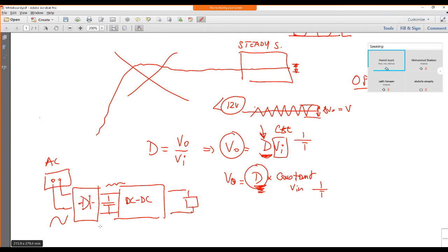Here we have two parameters that can suddenly change. The AC electricity can have any short circuit or any problem, and that 240 volts can go up or down. So this will follow that output here, because this one is not controlled. It's a diode, for example, and this Vin for our DC to DC converter will follow that change, going up or down.